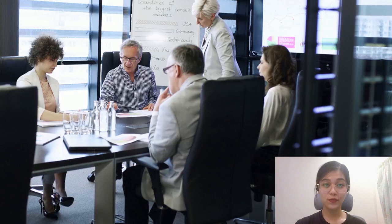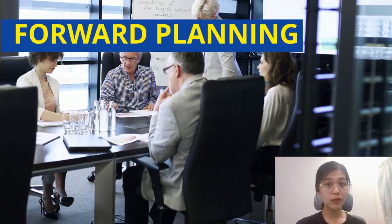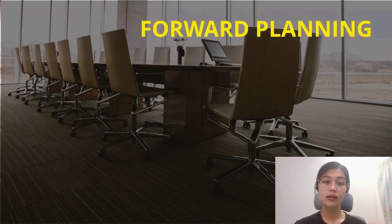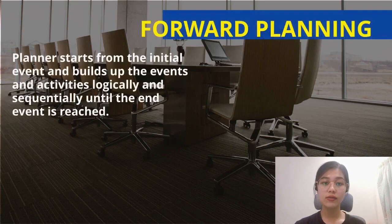The three types of planning. There are three types: forward planning, backward planning, and also combined planning. First one, forward planning. Forward planning is when the planner starts from the initial event and builds up the events and activities logically and sequentially until the end event is reached.